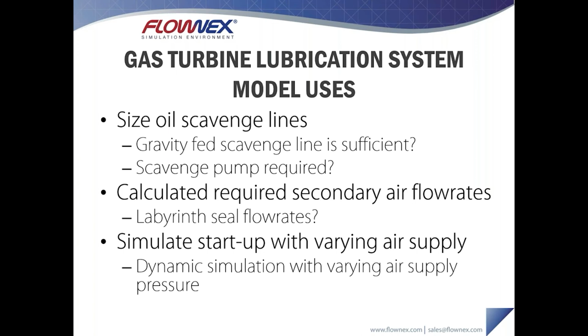And then the last thing is looking at some startup scenarios. As with all of our models in Flownex, we have the ability to run steady state as well as transient simulations. So we could look at varying the air supply pressure during the startup of the gas turbine and understanding what effect that has on the cooling oil flow rates, and seeing how the entire system behaves with these varying conditions.